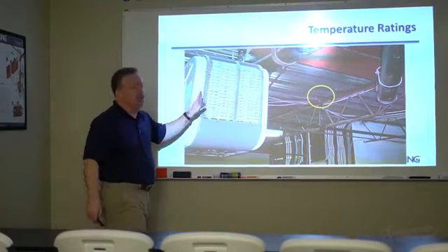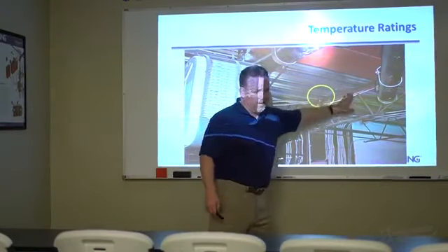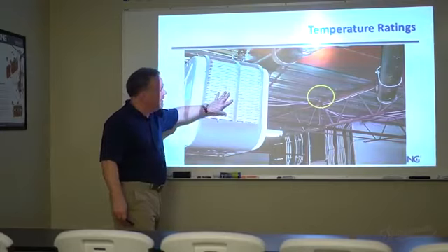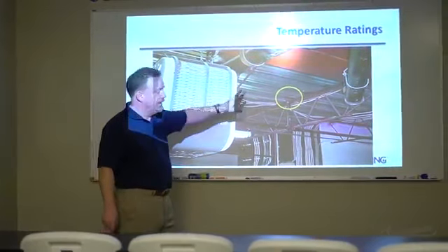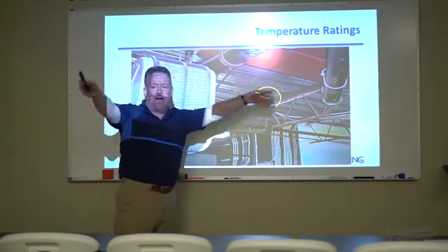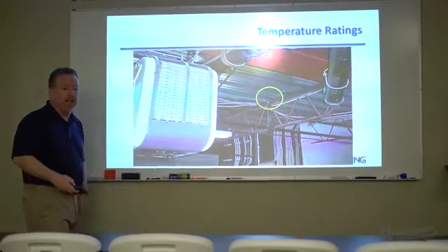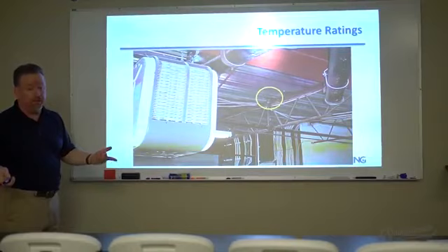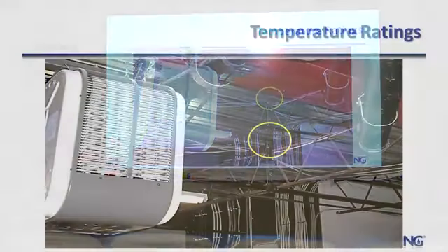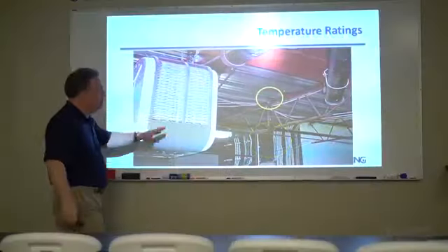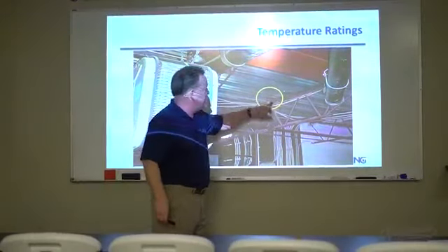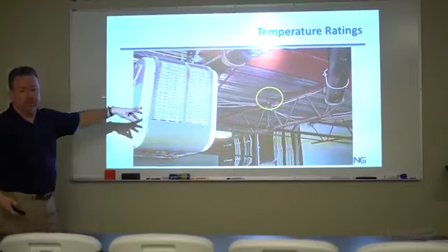Now, here's where we get into some of those localized areas that we were talking about before. You can literally have a unit heater blowing directly on, it blows out into the space. And because I've got sprinkler spacing requirements to deliver the water, I may have a sprinkler right in that given area, right in front of it, okay?